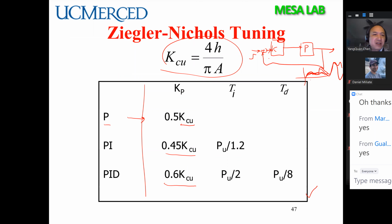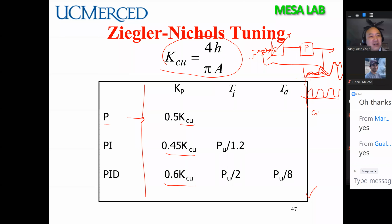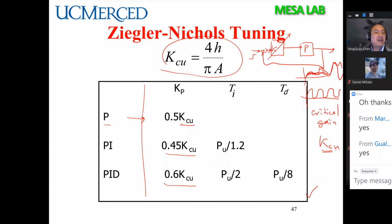But what if you tune the K such that your system is sustaining oscillation? In that case, it's not going up, it's not going down. So that K is called the critical gain, KC.